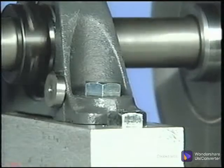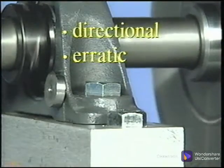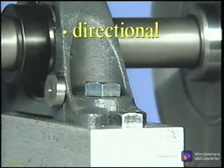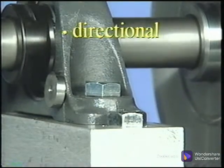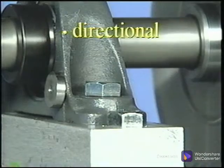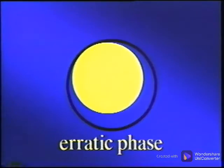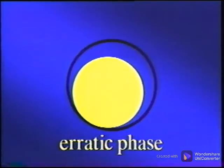Mechanical looseness can exhibit both directional and erratic phase characteristics. The directional phase is associated with loose bolts, mountings, base plates, and other non-rotating components. Erratic phase readings are normally associated with looseness in the rotating elements.